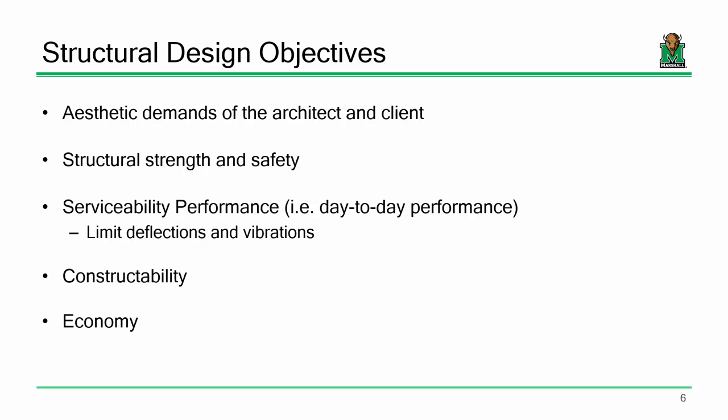Whereas, wouldn't it make more sense to just design like 4 or 5 beams and just use those same beams throughout? Make sense? That's why, we'll spend a lot of time on the design of a beam, but it's just something I want you to recognize. You might take that beam and use it 500, 600 times in a given building. So make sure that you're doing, not only an economic layout, but a practical one. I mean, do you want a beam to have 6 different types of rebar in it or 2 different types of rebar in it? What's going to be easier for a contractor to build? See what I mean? So it's just something to think about.